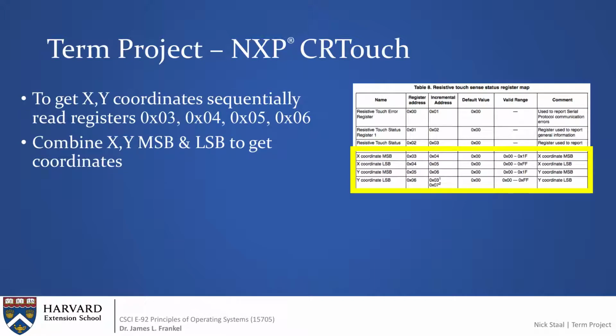The way it was transferred, basically you would be getting individual bytes. First they sent the most significant byte, then the least significant following that. To get the actual XY coordinates, you had to then combine those two bytes together.